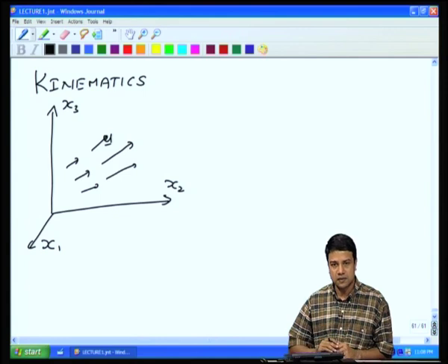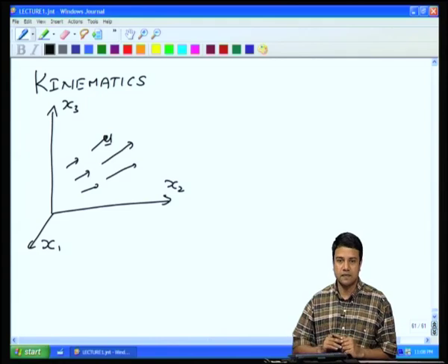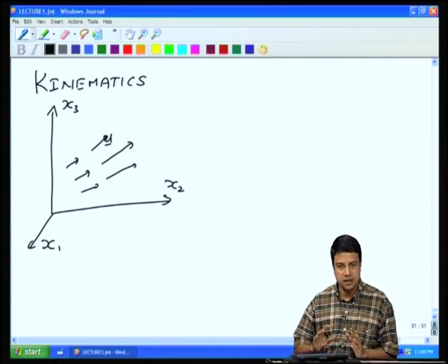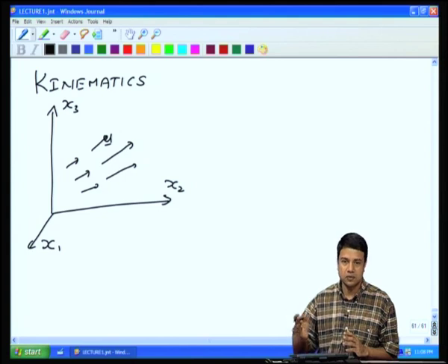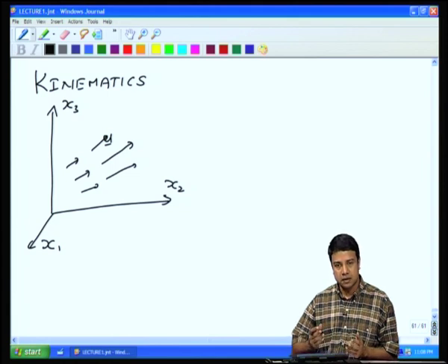We do analyze these of course in a fixed coordinate system with their components in those 3 coordinates, but however, this velocity field itself, as I have been trying to emphasize, has an identity which is independent of the underlying coordinate system. The flow in a pipe, for example, will continue to flow in that same direction regardless of what coordinate system I use to analyze that flow. So, we are looking at certain fundamental things about these vectors, which are invariant under coordinate systems. The magnitude and the direction are 2 such fundamental independent quantities.